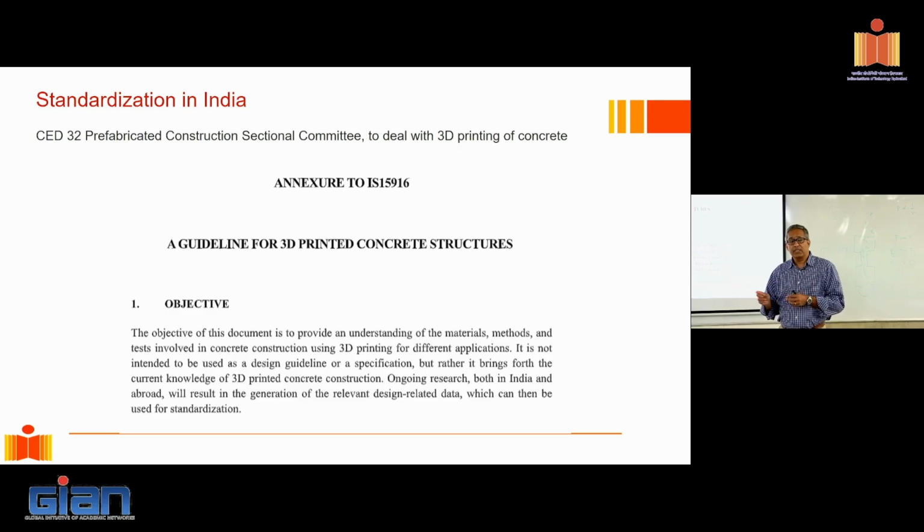Now, here is what this draft is very good at. They say two things. One is: use common sense, use established mechanics, and then go about designing. What established mechanics? Well, I already laid the case for you. Like what we did, am I justified in saying my compressive strength of 30 MPa is good enough for designing the concrete structure? The compressive strength in the weakest direction? Yes and no. You take a call. Okay. And that's what this code is also saying. The second thing it says, if all else fails, build a structure, test it to failure, then you know.